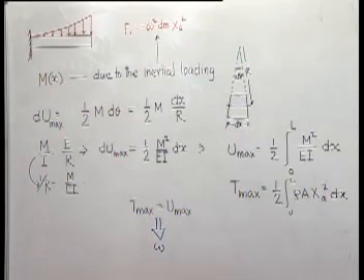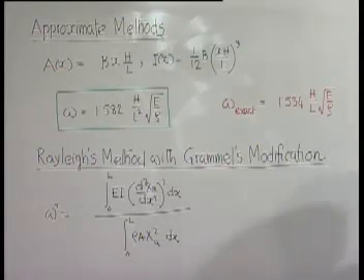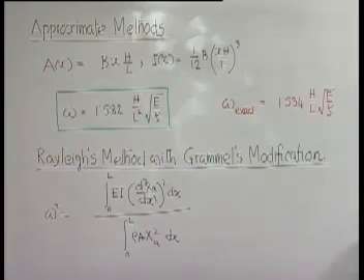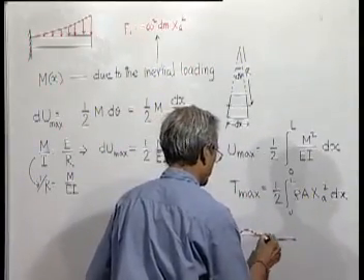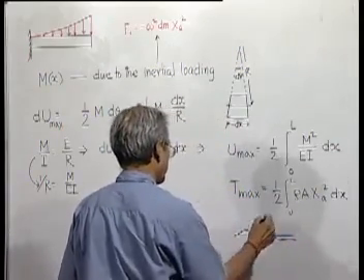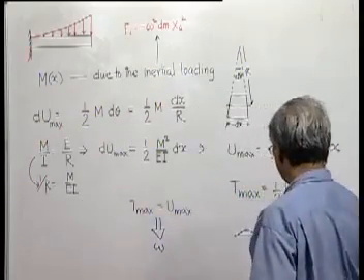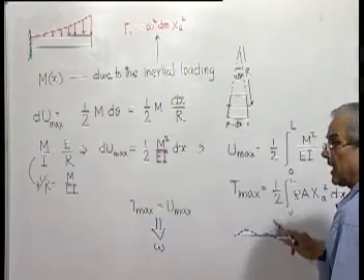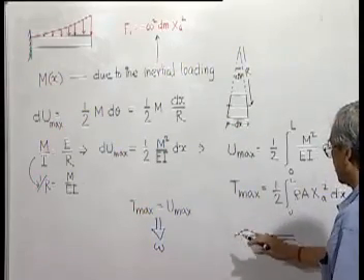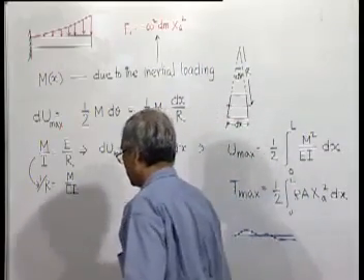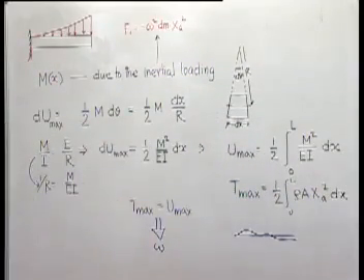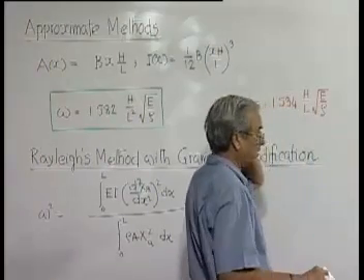The reason is this, that we are avoiding this double differentiation of X_A, which has been assumed. So in any kind of assumption of a curve, we know that the order of error in the slope will be more than the order of error in the actual function. And that is why we are now getting a better result, as we are doing the whole calculation without differentiating X_A.